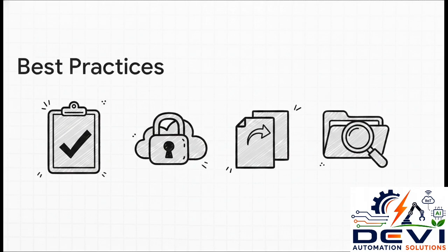Once everything is humming along perfectly, back up your parameters and enable password protection so nobody accidentally bumps a setting. If you're commissioning 10 identical conveyors, save yourself a headache and use the parameter copy feature. And finally, do regular testing and keep really meticulous documentation of your settings. Trust me, future you will be very grateful.